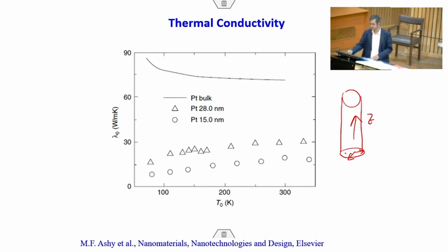Now, it can be as high as 3000 watt per meter per Kelvin. As you know, for pure copper, the value of thermal conductivity is only 400 watt per meter per Kelvin. So there is a substantial increase of the thermal conductivity because the confinement effects are not taking place in the z direction, because the dimensions in that direction are very large. So phonons and electrons can easily find ways to move faster, and they can conduct heat very fast. Nanotubes may not have many free electrons available, but phonons will be contributing a lot to the thermal conductivity.